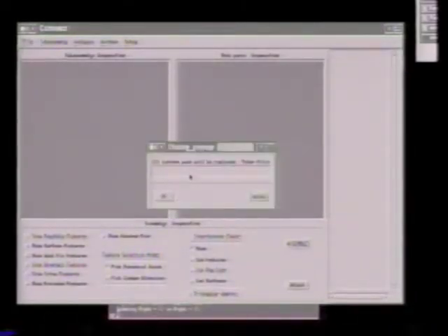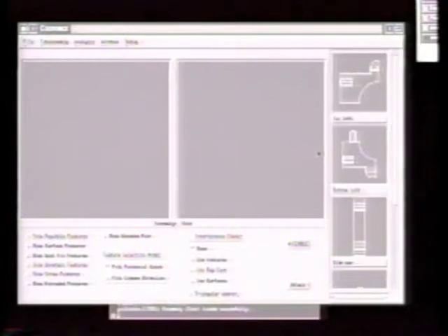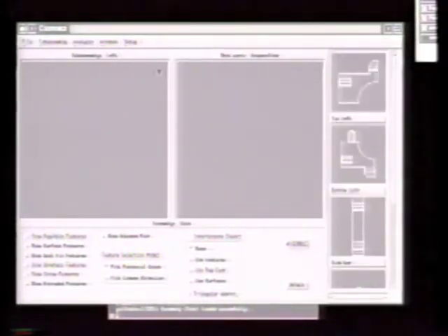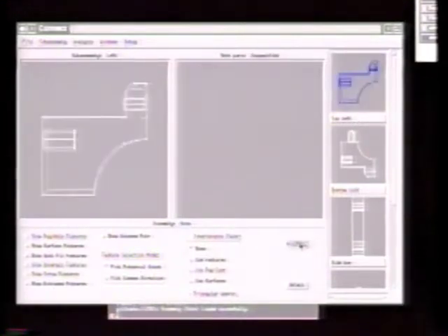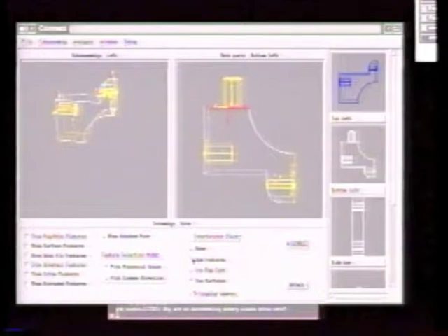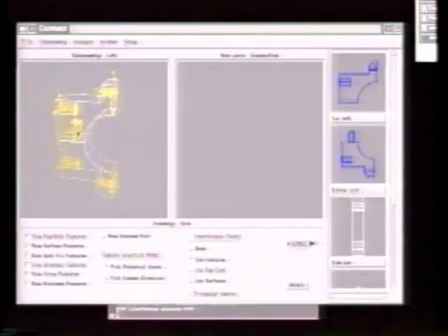This tool takes the assembly description and allows the designer to specify how parts connect to each other. The subassemblies are presented as specified in the planner. Small windows on the right contain the components of the current subassembly. The components are connected by specially defined assembly features. Defined features include surfaces, dovetails, pegs, holes, and others. If interference analysis shows that a part's geometry is not quite correct, the part can be redesigned and the new geometry substituted in.